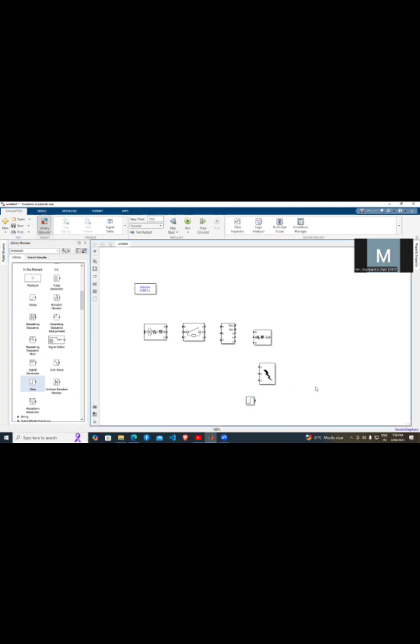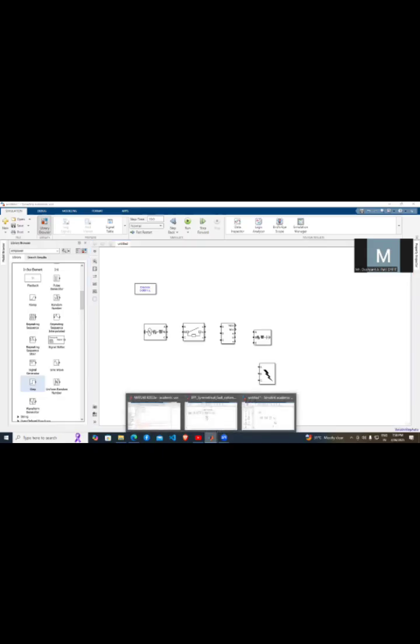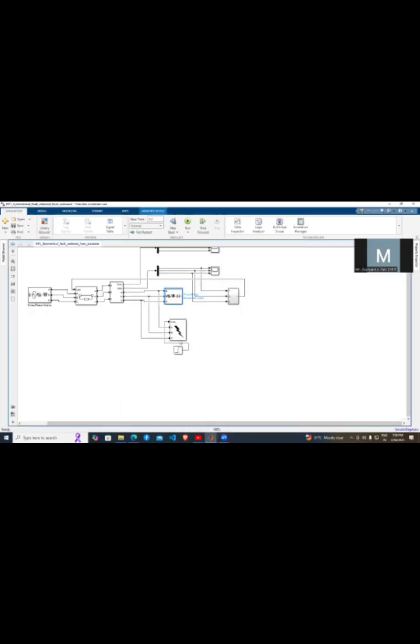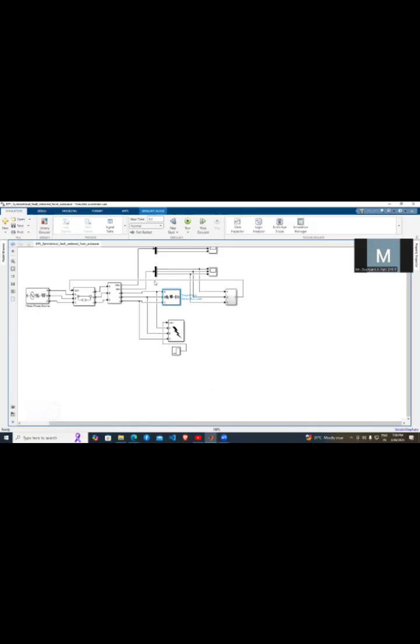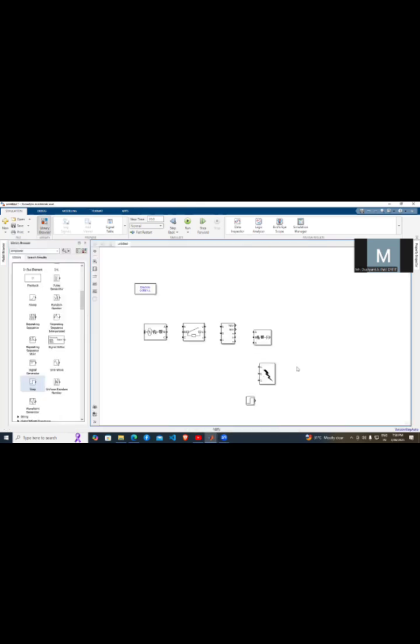Okay. Now after this, we have created the step function. Now after that, we have to measure the input signal of voltage as well as current from the measurement block, which is to be given to the demux. Demux means one input and multiple outputs, and we also require a scope function. I will tell you how to obtain this.